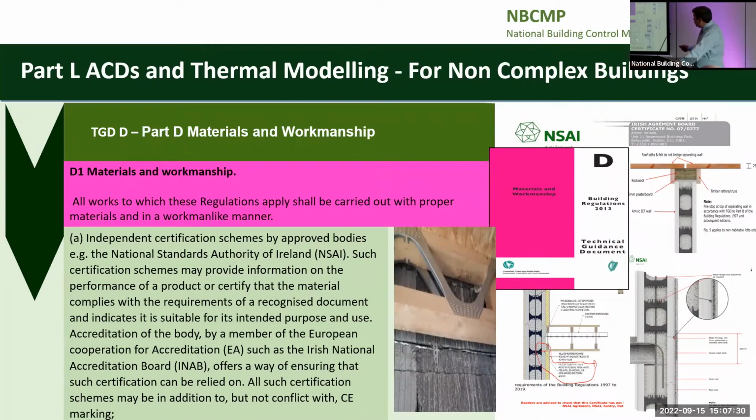You know, it's a small wee note and it's just a fire cavity barrier shown put in place. But it's important to have these details and these notes and understand them as well. And that's why competent people that are trained in this are highlighting those details, and designers need to be reading the notes as well, because they may have implications for other things.